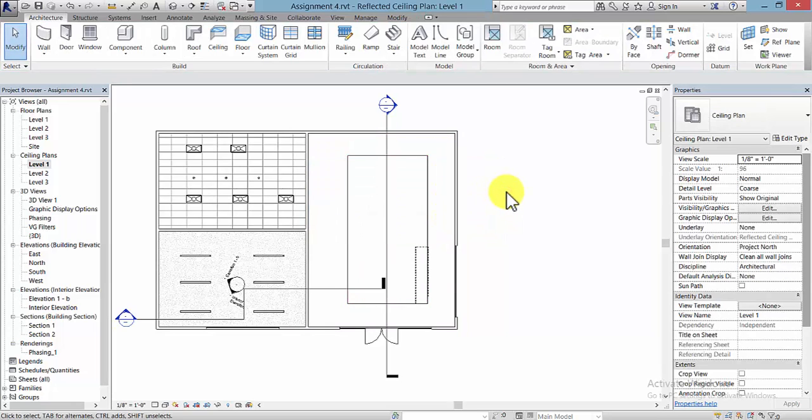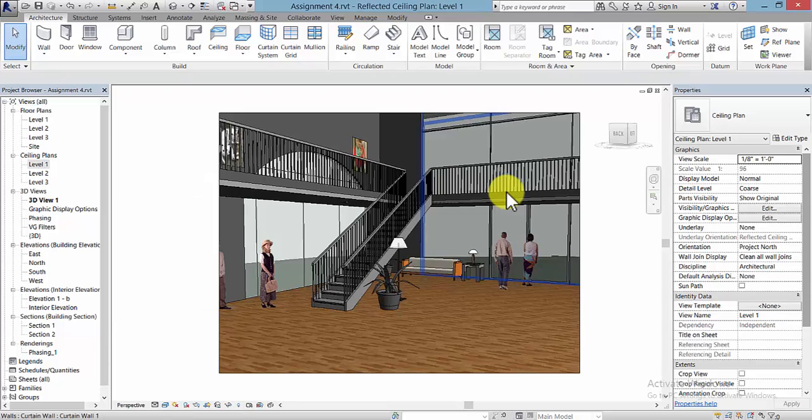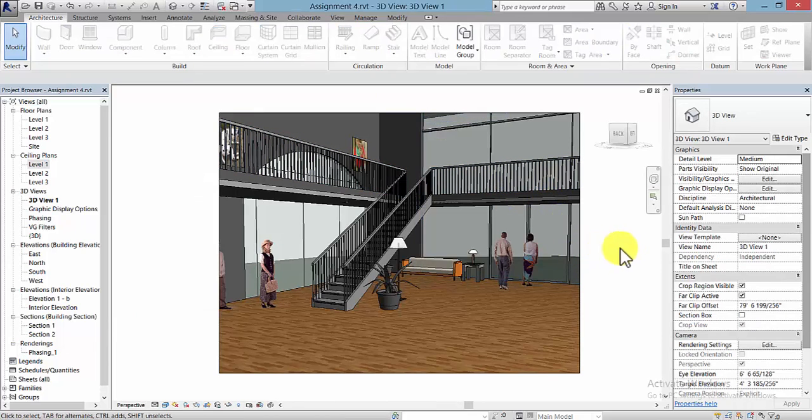You can tell I'm going to use Control Tab, which will help you cycle through the views that you have open. There's that piece right there that's up against the flooring that becomes my chipboard. And then I used component, place component, to place a couple of recessed lights here.